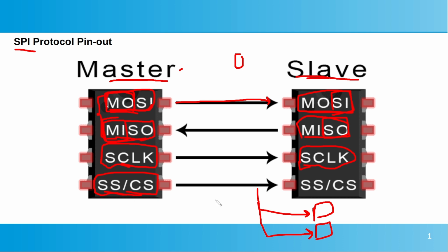So once this pin is pulled down, the connected slave will be active. So this is an active low pin. If this line is going down for this selected slave, it means the master will communicate with this one. If this line is going down, then this is the slave to be used to communicate with our master, and so on.